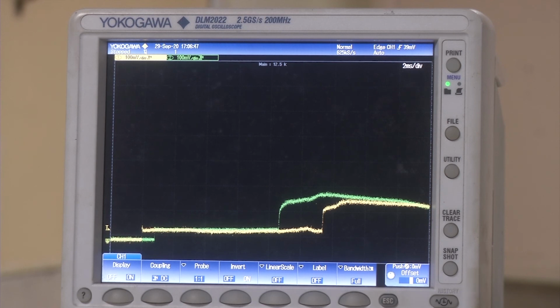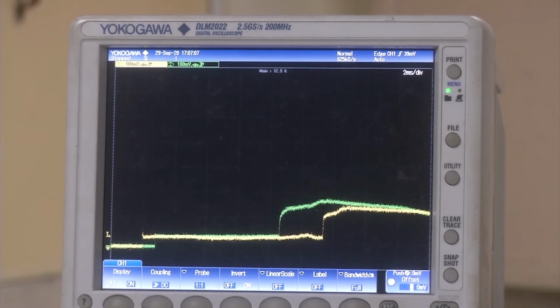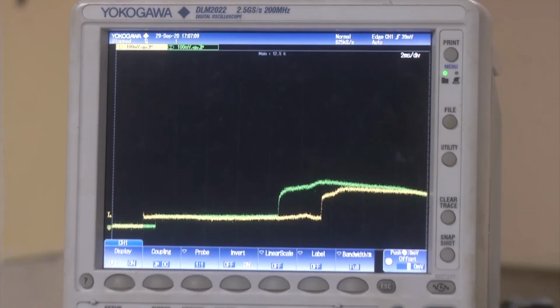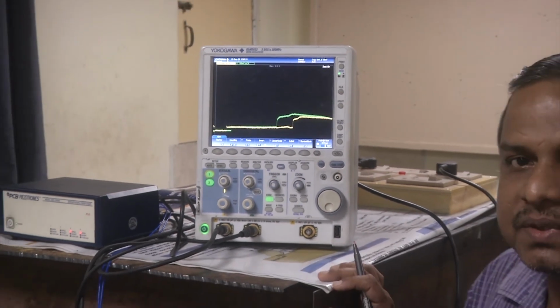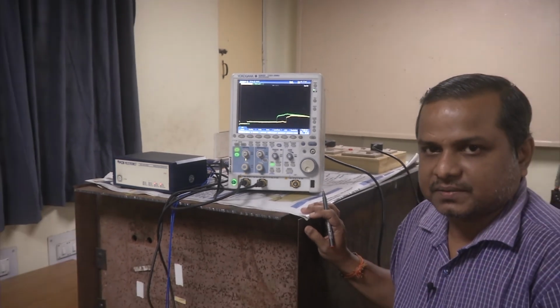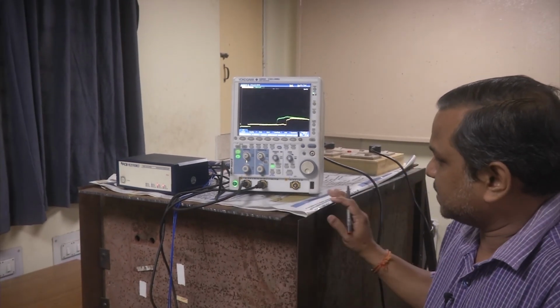At the outset, I can conclude this demonstration by saying that a shock tube can be considered an impulsive facility for generation of a high speed slug of mass for a short duration of time. And its main application, as you can see here, we have also attached a section which is used as an enclosure to study the deformation behavior of metals, which is not part of this course.